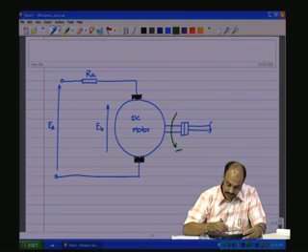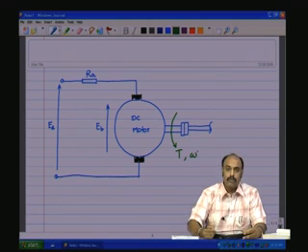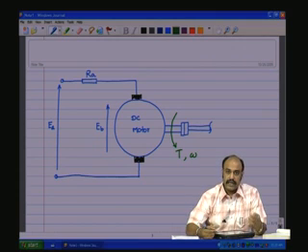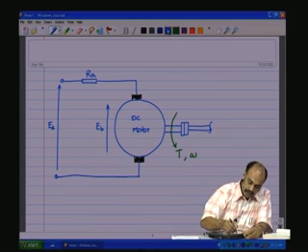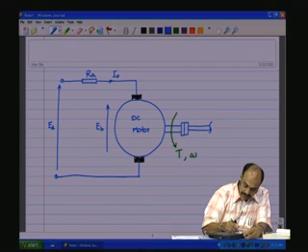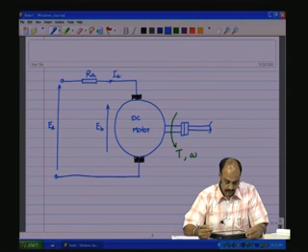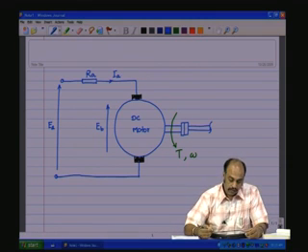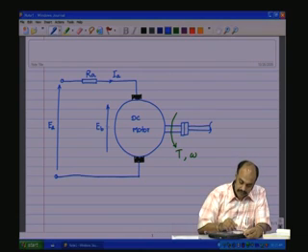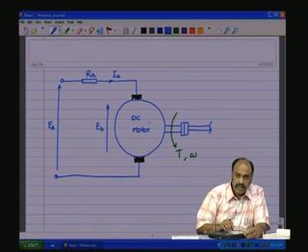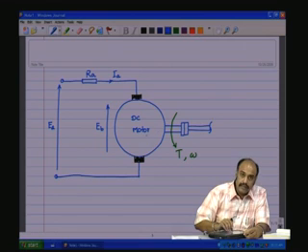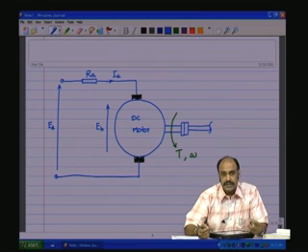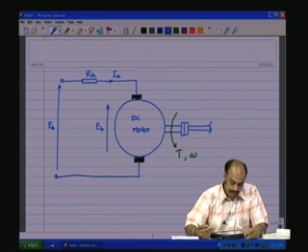That is, one is the torque, which is the potential variable, and the other is the omega in radians per second, which is the kinetic or the flow variable on the mechanical side. And the flow variable on the electrical side is IA. Now, EB into IA is the power delivered to the armature, and that is going to deliver the rotational power to the mechanical side.